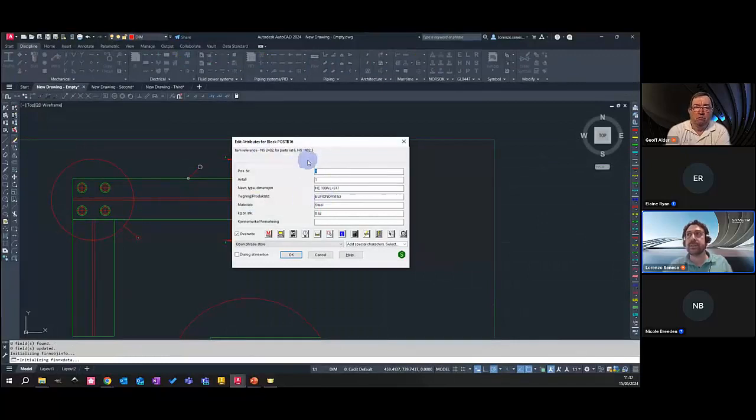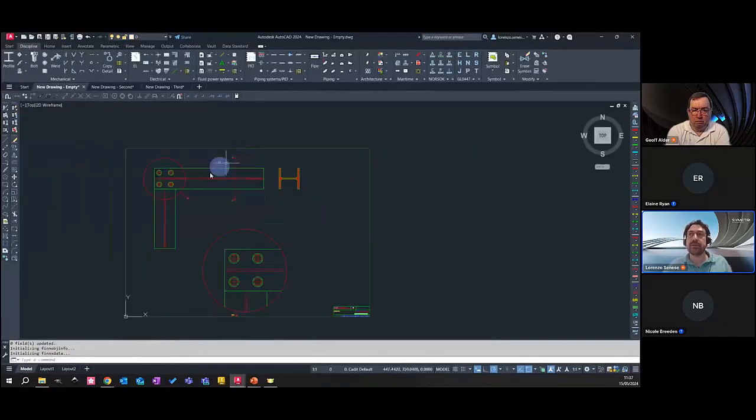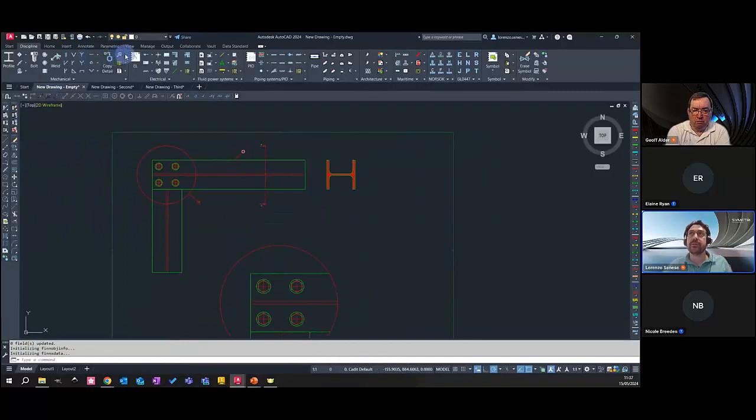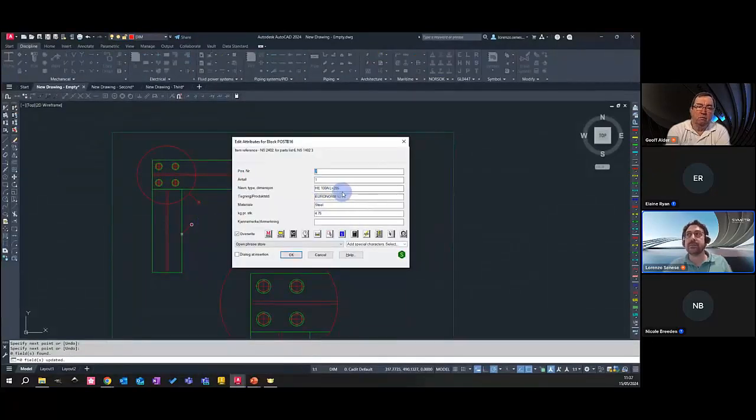Okay. And you can see that is also recognizing the length of my beam. So I don't need to type the length, is just giving me also the length, the material, and as a consequence I have also the weight that I can use, for example, later in my part list. And I can change all these things. I can click OK. So they are all attached with this component. I'm just going with the other one as well. So I'm adding a balloon for this component in here. Okay. And I can see here is changing as well. So accordingly with this one selected.